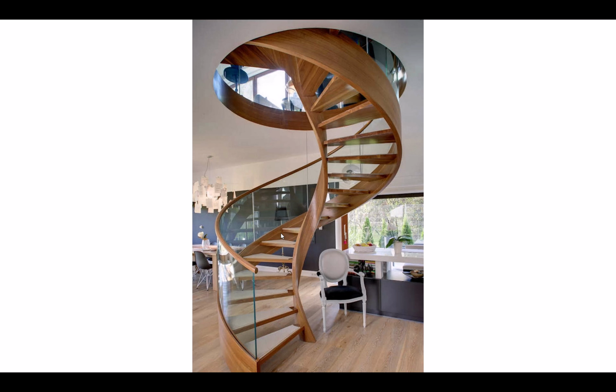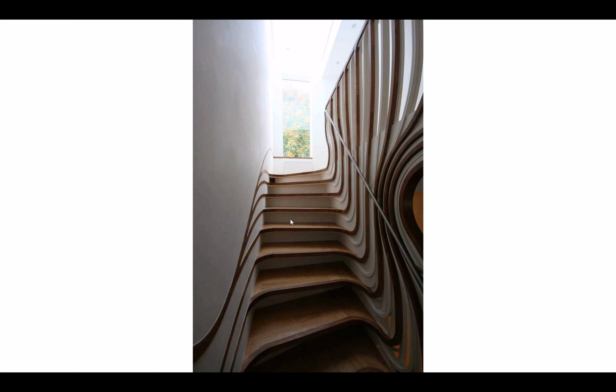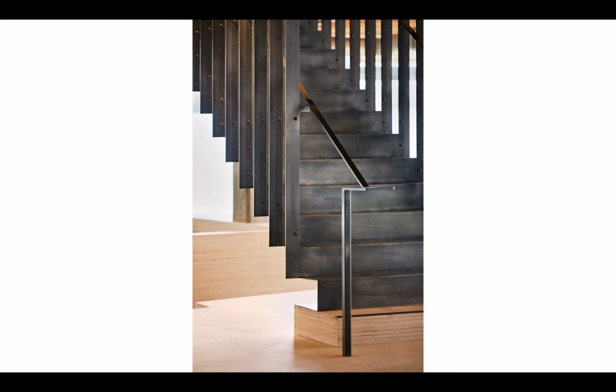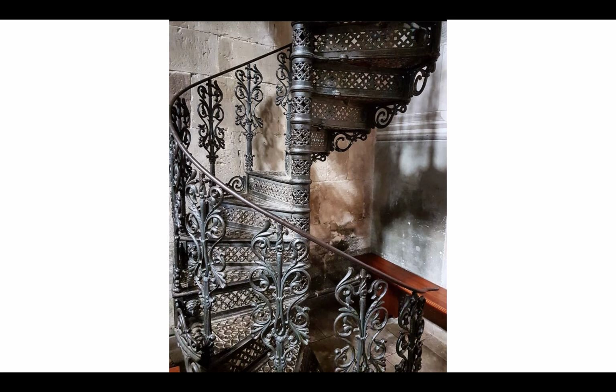Revit just does not like railings to be evenly spaced. It will space them evenly, but it will often leave gaps. And then once you get into super custom sorts of things, you're absolutely going to need to leave the standard stair world and start considering making very custom types of objects.